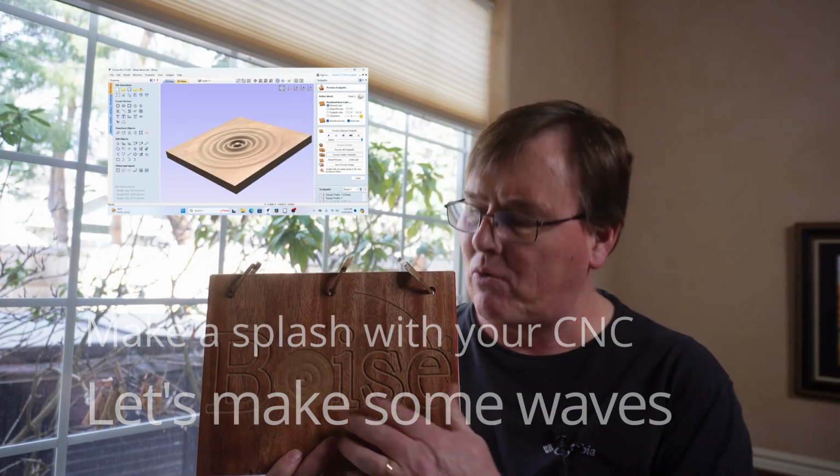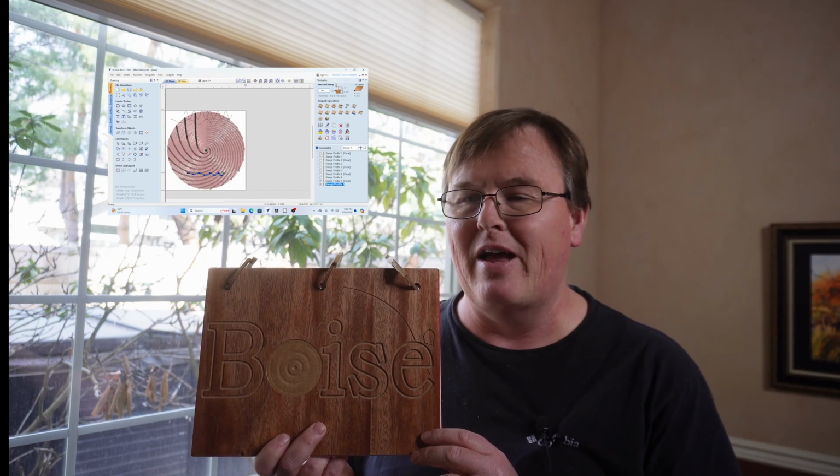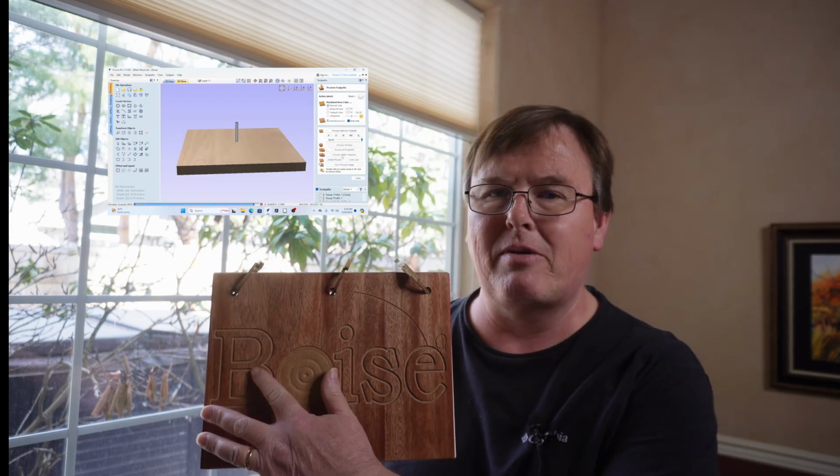Today I want to show you how to make a wave like a trout jumping in the middle of a lake or a rock being tossed in the water. It's a neat little trick here. All you're going to need is the texture tool path. You're going to need the molding tool path. We're going to combine them together. When we get all done, we can adjust the amplitude of the wavelength of the wave, and also we can adjust the total diameter of the circle.